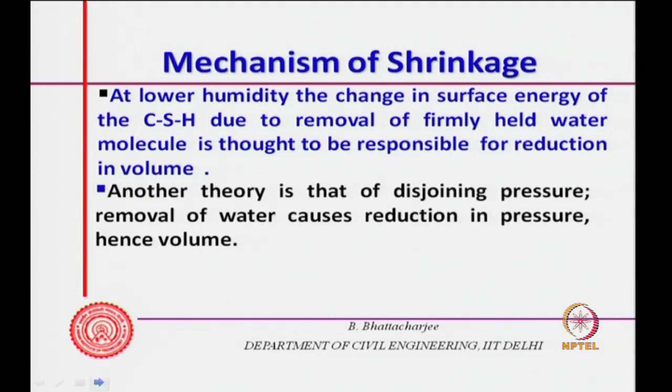So, there is another theory. The first one was the capillary tension theory, as we said. The second one is surface energy. As we are removing the water, surface energy changes would occur, and that results in a reduction in volume, and that is why shrinkage occurs.